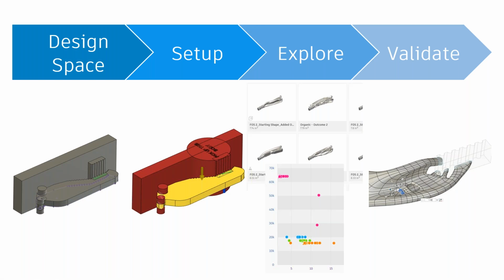We will show how to modify them a bit, because probably one thing that I forgot to mention that is very important: the outcomes from generative design are a solid model that you can very easily modify for doing a kind of fine-tuning for preparing them for production. You can modify them in Fusion 360, but if you prefer, you can bring them back to Inventor.